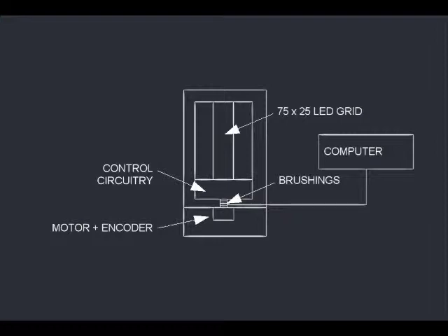Hi, my name is Eric Finlay and I'll be talking about the electrical component of our project. The original electrical plan is as follows. There will be three main components: the motor, the LED grid, and the LED control systems. The motor is going to be powered by a 12-volt laptop power adapter. The speed is going to be controlled by a half H-bridge. It is unclear at this time whether the motor will be controlled by an encoder or held steady at a pre-specified speed.